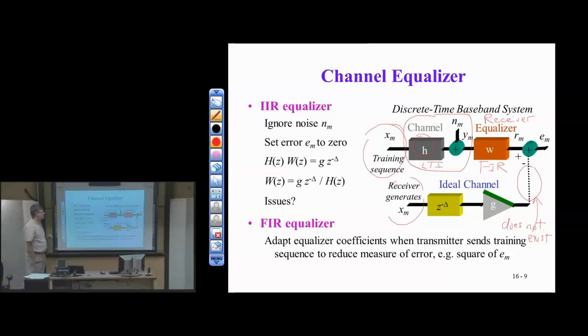That gain is a result of the channel and equalizer. That's correct. Now, we can set the gain to 1, which we'll do in homework 7.1, 7.2. And we're going to search, because we don't know the delay. This delay is a transmission delay. We don't know what that is. Now, we can have an idea what that is, because I can correlate the training sequence sent by the transmitter against the regenerated PN sequence at the receiver and find the transmission delay. So I have some idea what this is. Now remember, this is a transmission delay after equalization. So it's the transmission delay through the channel plus the group delay through the equalizer.